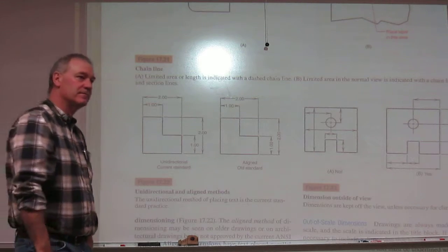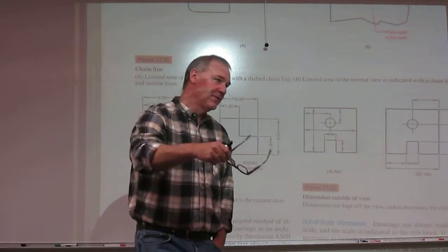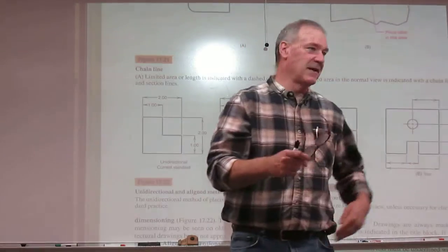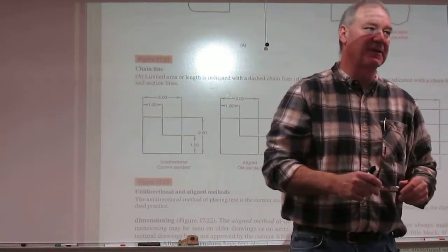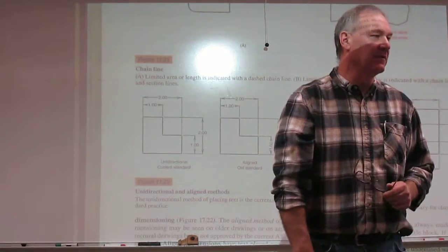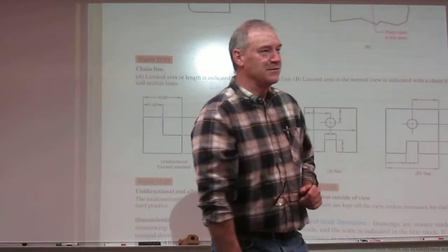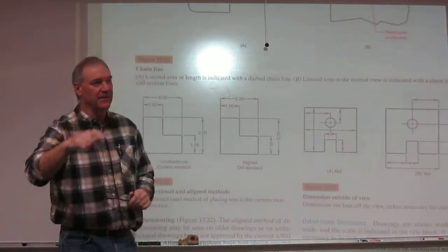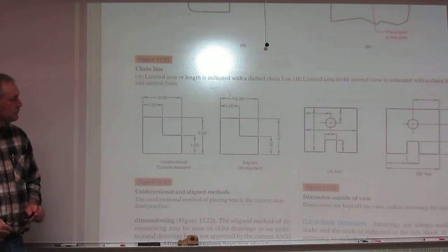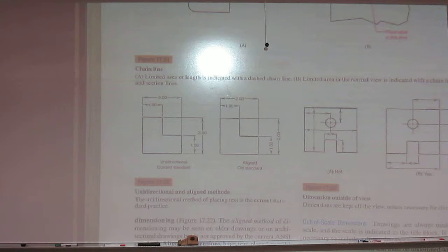Since you're coming from 1/4 to 1/8 text, you're kind of in that gray area right there. Just stick with 1/8. Give it a little separation. And then you should be 1/16 between all the rest of it. All right, so for us, text, we're unidirectional.